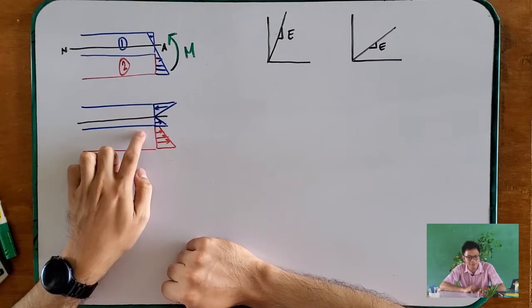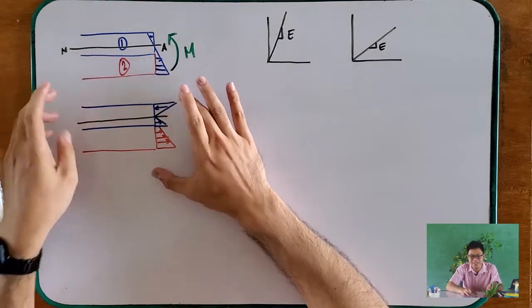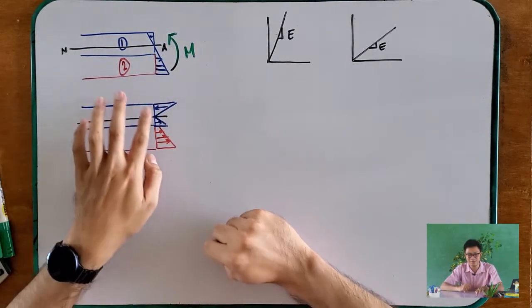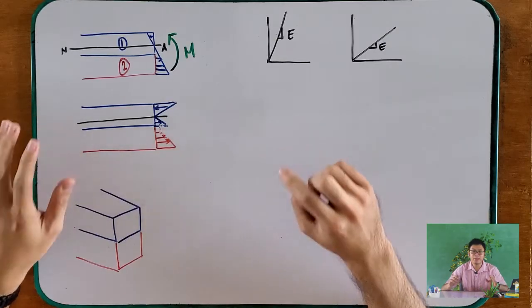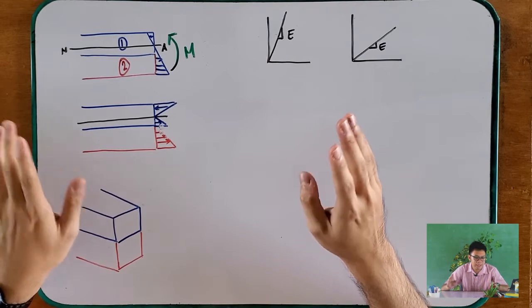So, how are you going to graph the profile view? Basically this one is your profile view, the side view of the behavior of the stress. So how can you graph a profile view of a composite material? Our goal is to apply the flexure formula to this beam. But again, we cannot apply the flexure formula because this beam is not homogeneous.